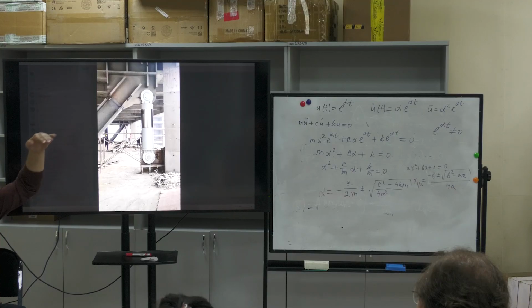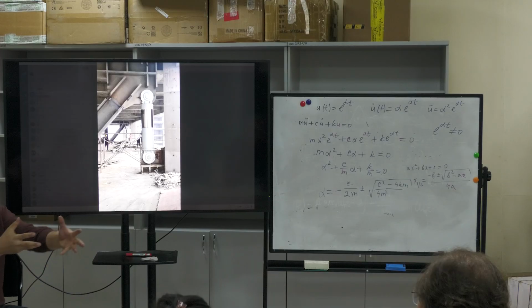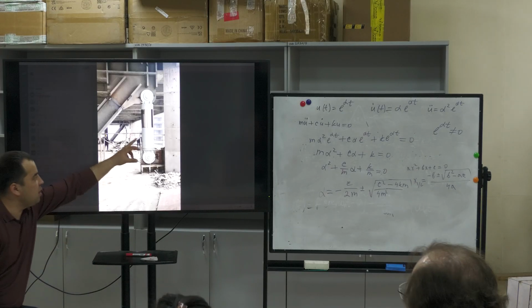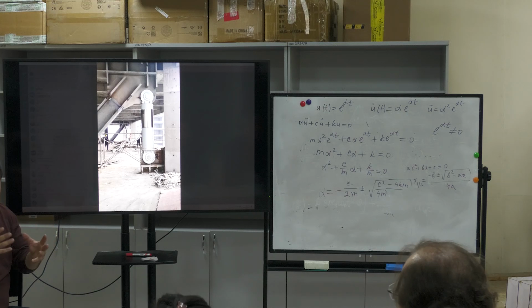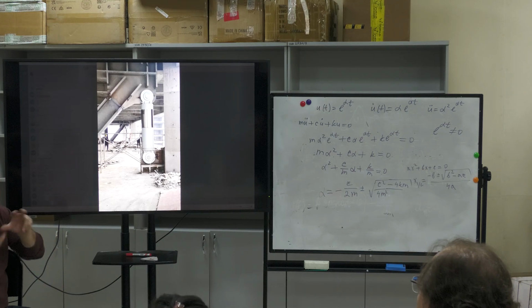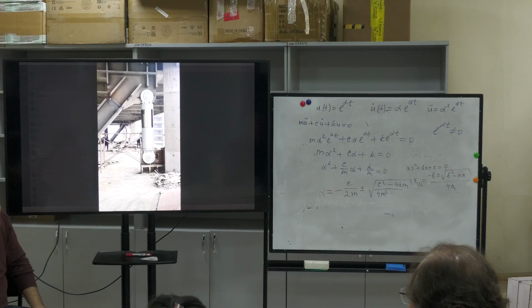It is a 30-floor building overall. In every 10 floors they install this kind of damper. Why do we need such a damper? If an earthquake occurs, all the energy from the earthquake will be absorbed by these dampers, okay? Dampers are energy absorbing elements. After some movements they remove all the energy, the oil inside the damper is heated up, and all the energy changes to heat. Then our building is stabilized after the earthquake. That's the reason we need the damper. Clear?